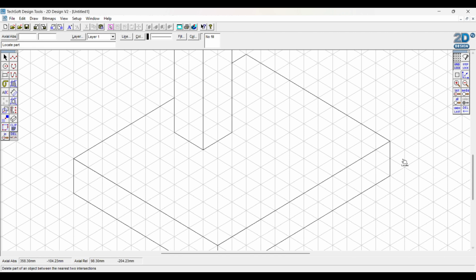To make the T-light holder in the base, select the Circle tool. Remember that when drawing a circle in 2D design, you start from the centre. So find the midpoint and draw a circle with a 20mm radius.